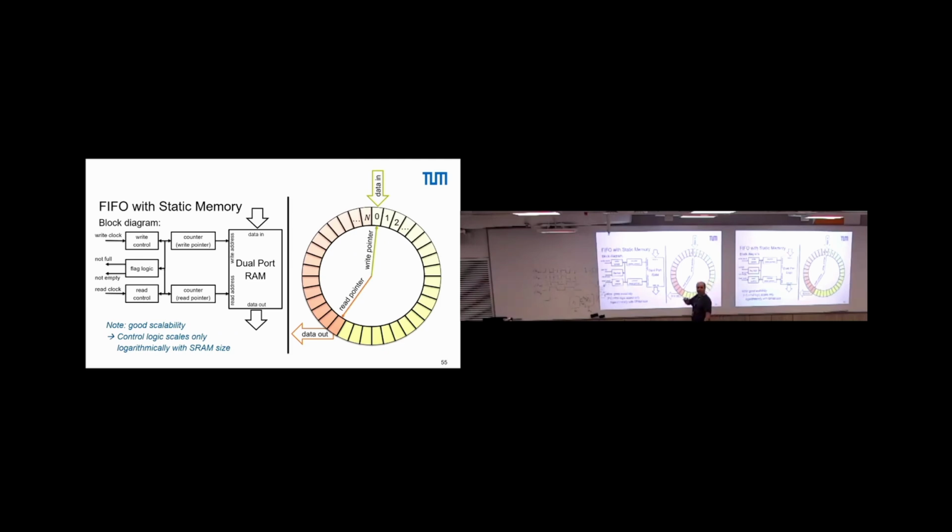The second thing is, if they run on different clocks, and by chance, B is on a lower clock than A. So we have this case here, right? The write clock is much faster than the read clock here. So it's twice the speed. So I can write 2 data words before I can read 1.